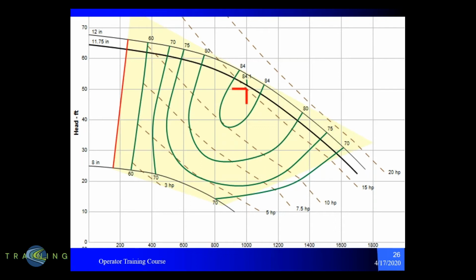So the same pump, different head condition, has a completely different performance output on flow, and that's really important to understand. If you notice in this one, at the red arrow, we have selected a duty point of 1,000 gallons a minute at 50 feet of head. So this specific point fits very well in the middle of the curve.